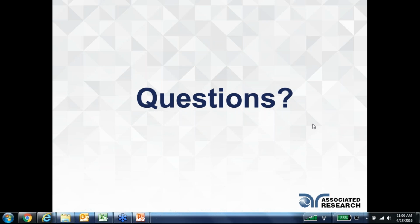Let's see, Nelson's good. And Abel asks, do you think UL 471 will use your current leakage tester? UL 471, no, standards don't call out what tester you can and can't use. As long as those instruments meet the requirements, whether it be transformer requirements or current limit requirements, you should be able to choose any instrument you want.